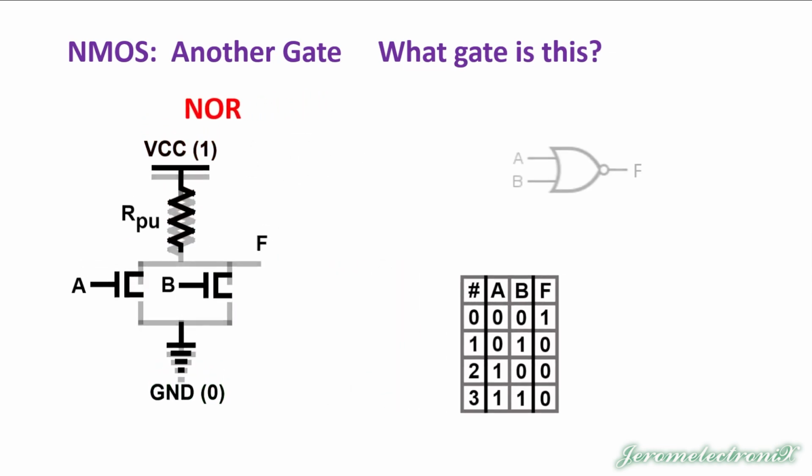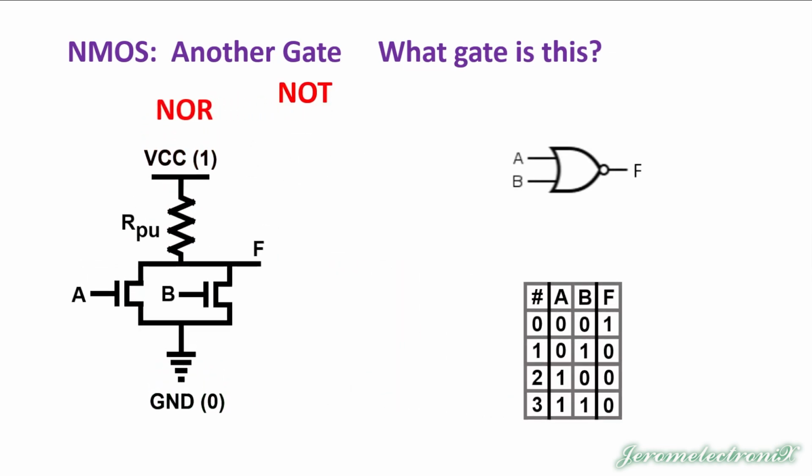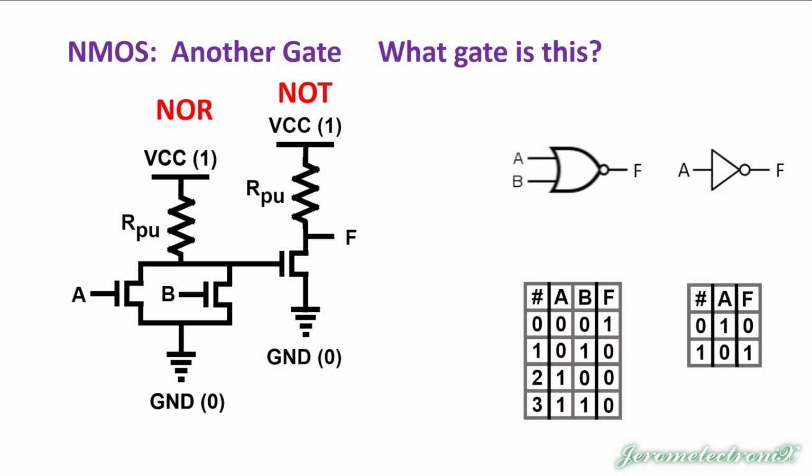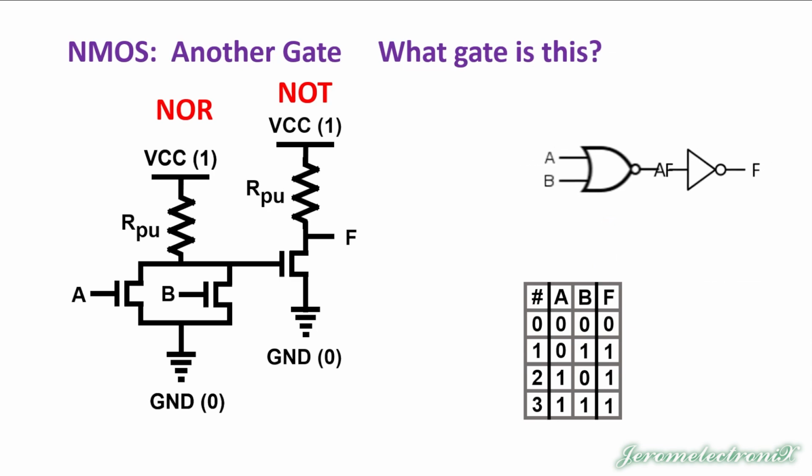Looks like this. And, of course, we've got to convert the NOR gate to a NOT gate, so I'm installing an NMOS pull-up NOT gate on this, which will reverse the outcome on the truth table. And so we're just reversing the outcomes on the truth table really quickly because we're knotting them as they come out.